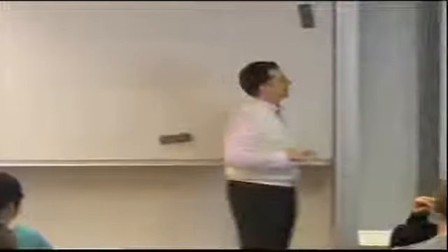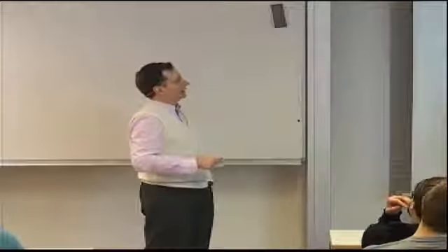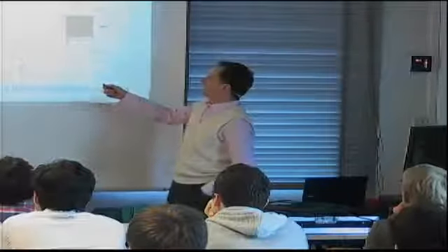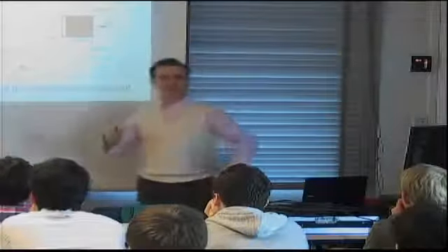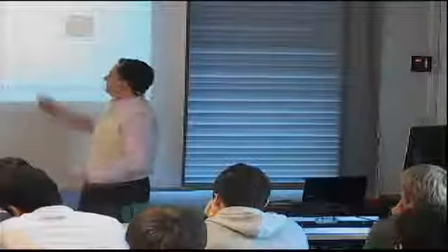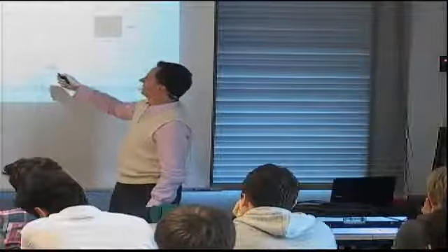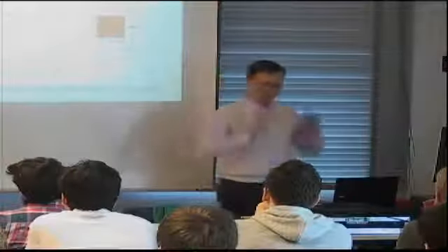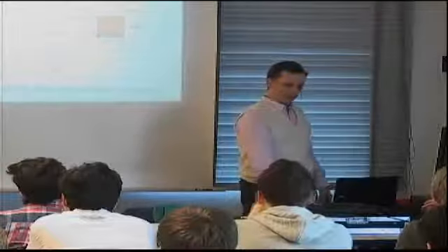Now, the only reason that our designs might have a difference is when it comes to damage tolerance. Remember my stacking sequence, or our stacking sequence. Well, let's look at this. In one case, I have 0/90s on the outside. In the other, I have plus or minus 45s. And I have three 0/90s in the middle here, while here they alternate. Now, there are reasons why one would be better than the other when it comes to resistance to impact, and then what's the compression after impact strength. We'll talk about those in the next course because it's lectures and lectures' worth of discussion.